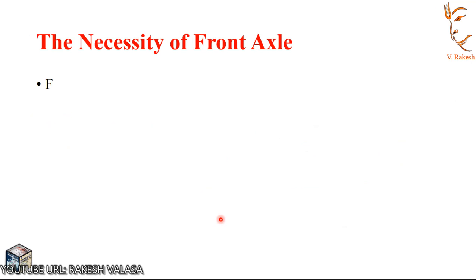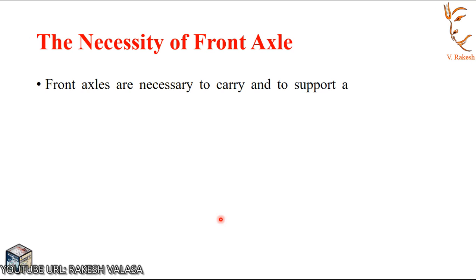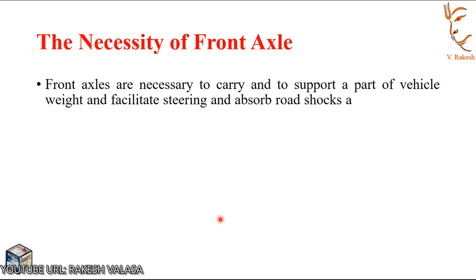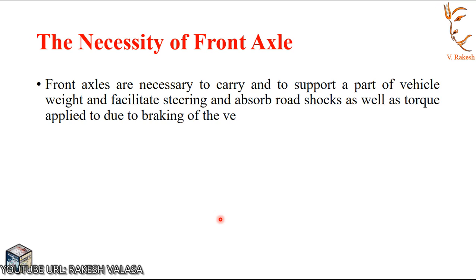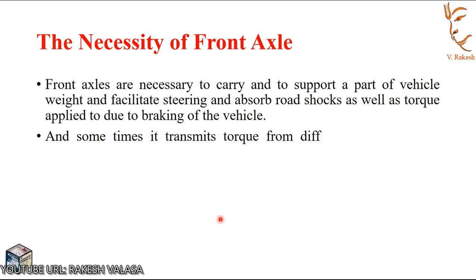The necessity of front axle. Front axles are necessary to carry and support a part of the vehicle weight, facilitate steering, and absorb road shocks as well as torque applied due to braking of the vehicle, and sometimes it transmits torque from the differential to the drive wheels.